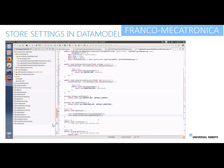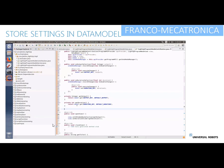However, in our case, the IO combo box will by default be empty. So we also need to configure the IO combo box to contain the appropriate items. There are in the UR control box 8 digital outputs, or standard outputs, in the controller. These are named from 0 through 7. Now we want to create a method that returns a list of these outputs that the view can show. Hence we'll create a private method that returns an integer array. We can call it getOutputItems.